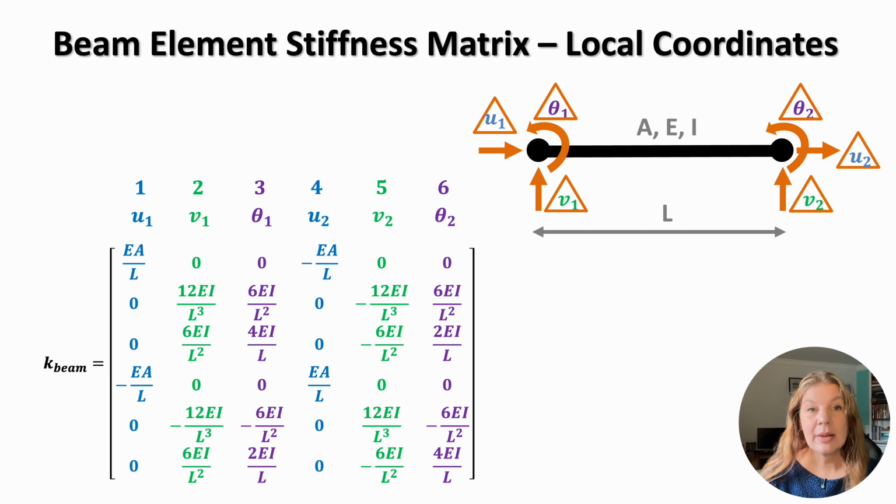We take each element matrix, identify which global degrees of freedom it connects, and then add its contributions into the global system. The process relies on a consistent numbering system for nodes and degrees of freedom. Once this mapping is in place, the assembly becomes systematic. Each element matrix is slotted into the right place in the global matrix.